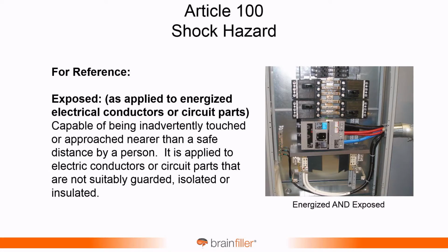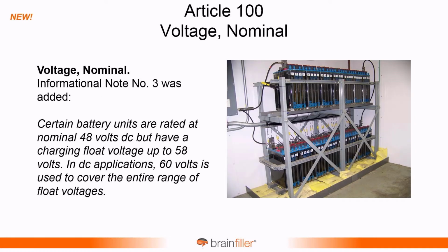And part of this is there's actually a definition within NFPA 70E for the word exposed. This definition has already been there, and it's for conductors and circuit parts capable of being inadvertently, that's a key word there, touched or approached nearer than a safe distance. And so this definition is there, and the word exposed has been added to the shock hazard.